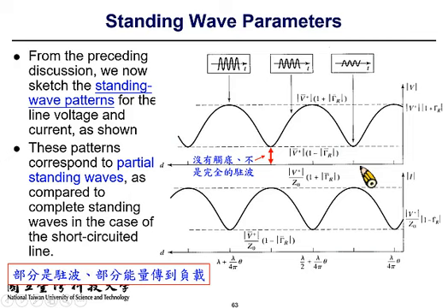So from this pattern, we can say that the transmission line has a standing wave part that goes up and down, and also a traveling wave part, because the minimum does not touch the bottom, so some of the energy is delivered to the load, just as the remark here says. But anyway, as long as there is some mismatch on the termination, as long as the reflection coefficient magnitude is non-zero, you will observe the so-called standing wave pattern.